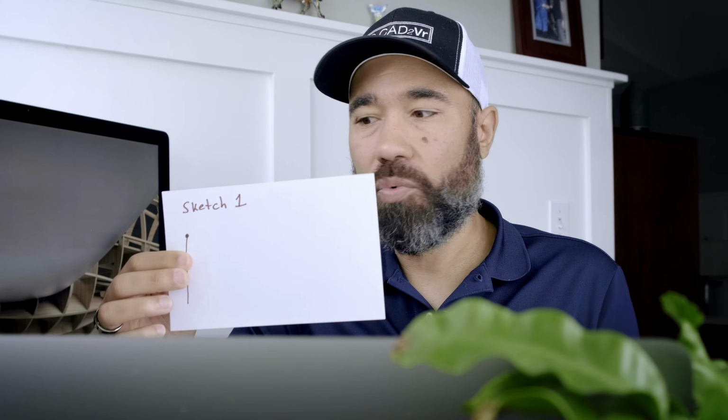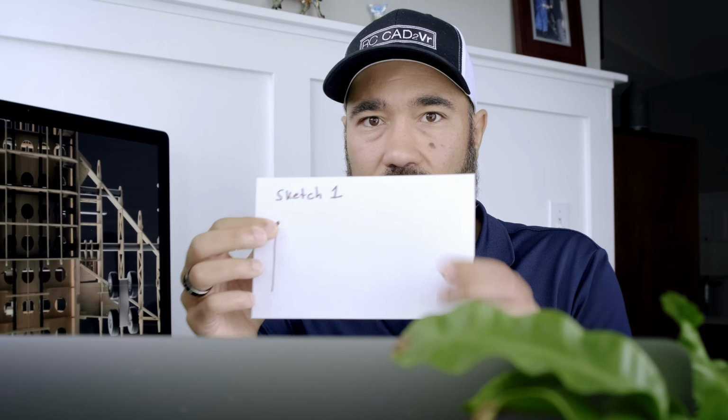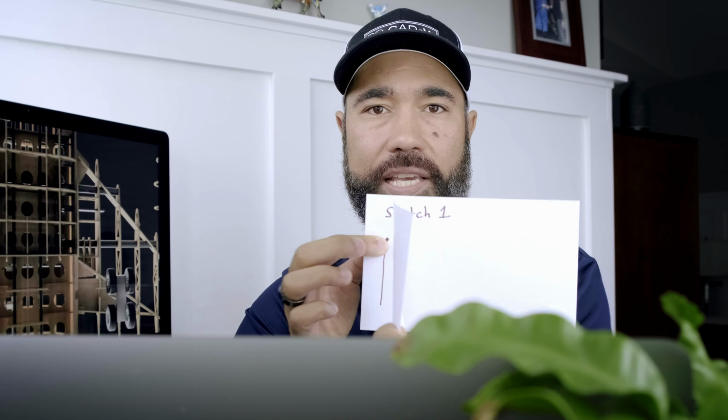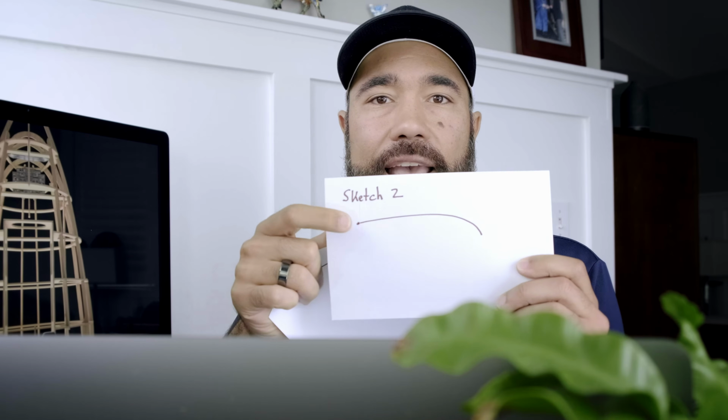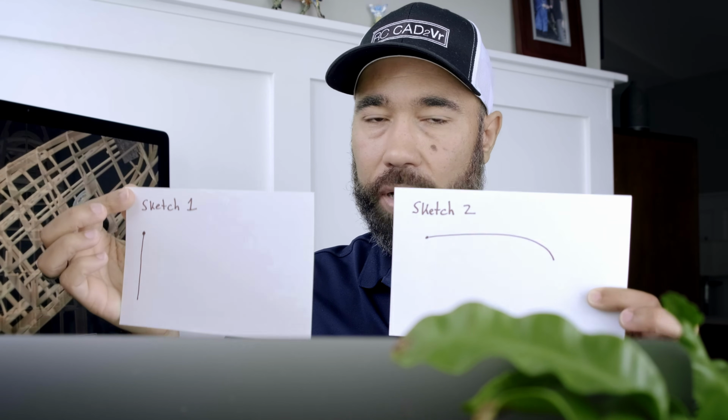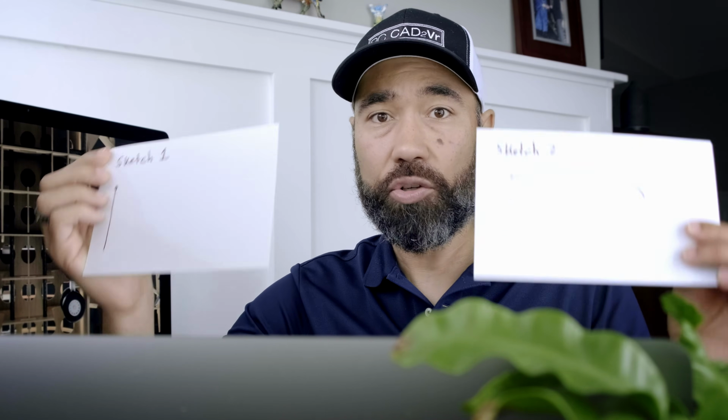And so basically what we do is we take this node right here and then we'll end up projecting it over to here. So all of a sudden we've got a node that is on this sketch independent of this one. Now I realize that sounds a little bit convoluted, but you have to remember that when you create a sketch, it is on its own single sheet of paper or its own plane.